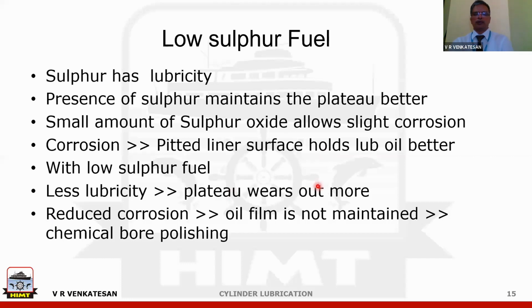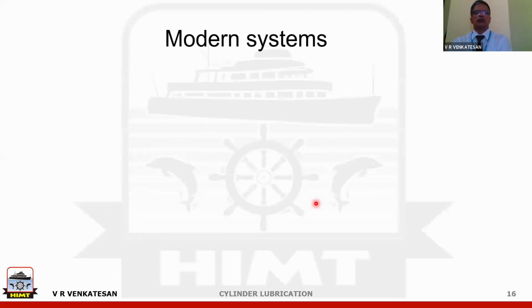The other type of bore polishing, which is due to carbon buildup, is called mechanical bore polishing. So bore polishing is something you don't want in liners. Traditionally, it was always associated only with carbon buildup. Now this low sulfur fuel is also creating bore polishing problems.